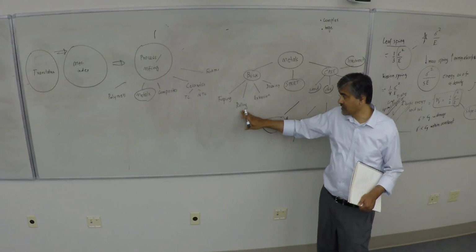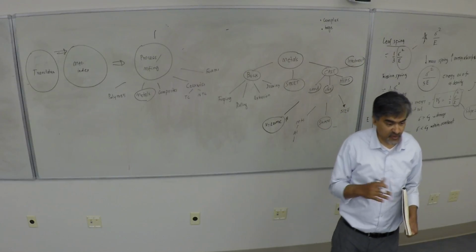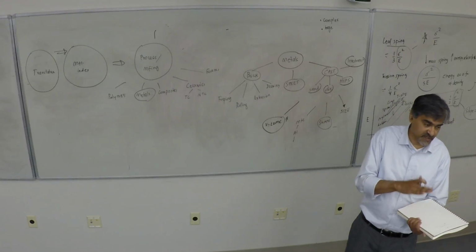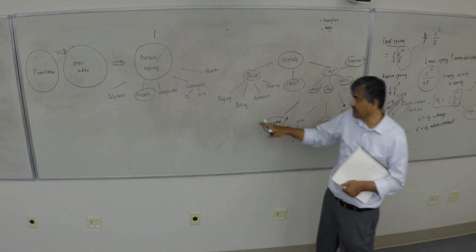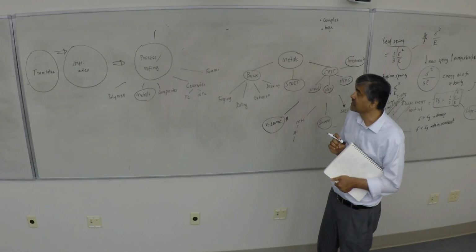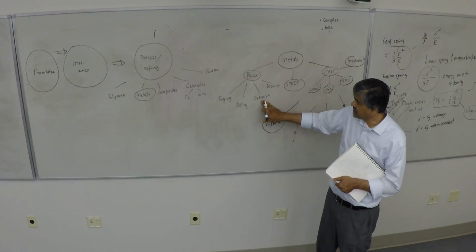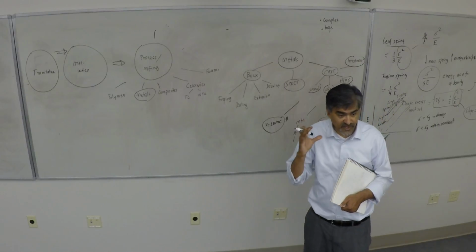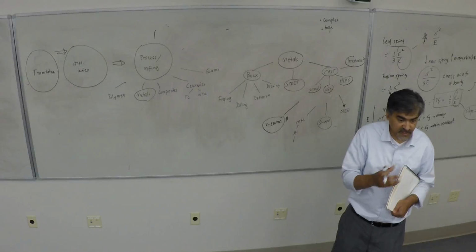When you look at rolling, like I said, again it's a deformation process, no volume change before, after, same. Now you start with sheets which are a certain thickness and start bringing them to a second thickness. Doing so, there's a lot of changes in the microstructure and the material condition which has to be accounted for. Extrusion, like you say, constant die. For the most part, you're pulling the melt from a green state through the die and then shaping it.